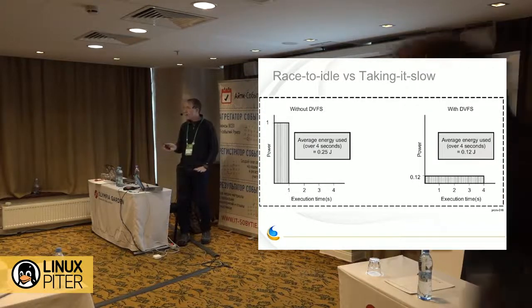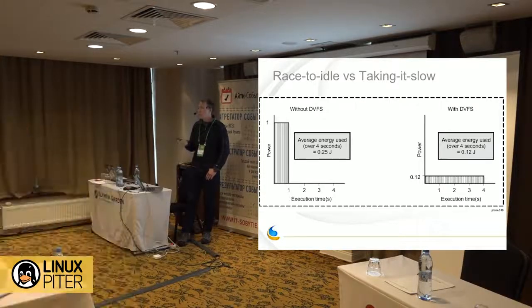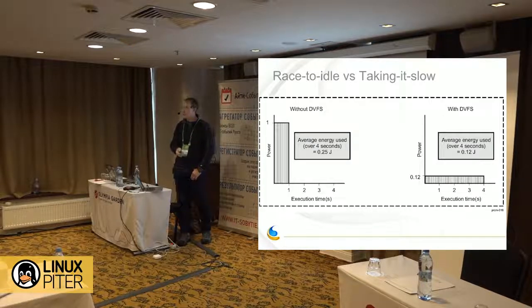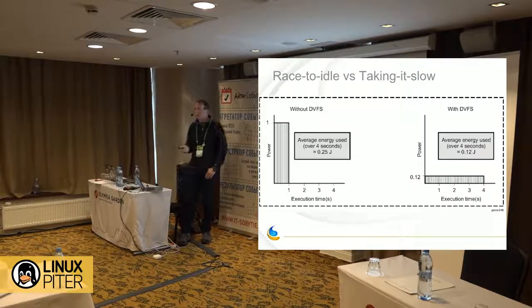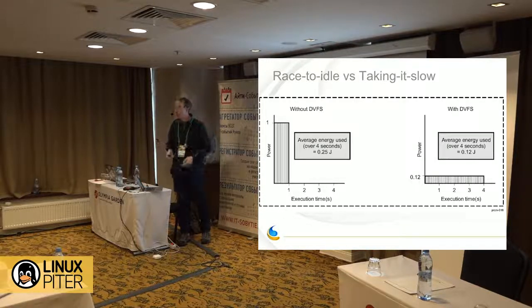There's not one that's better than the other. I see people debate race to idle versus running slow. It just depends on the use case, the architecture of the hardware, and what the workload is like. For instance, imagine the difference in software workload between a device with a touchscreen that the user occasionally touches, where you need some bursty performance, versus a data center with a server running a MapReduce type of workload.